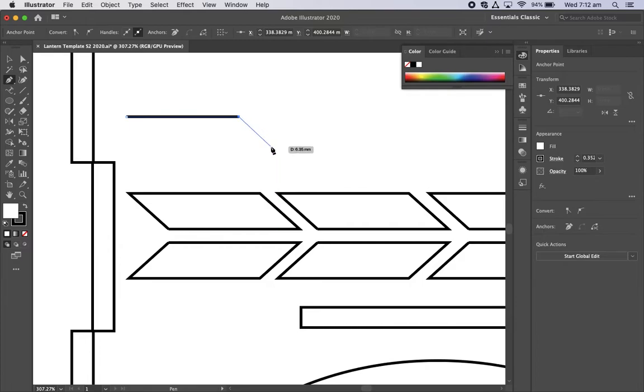Now I want to create a 45-degree line here, so I'll hold down Shift. Good. And at this stage, rather than trying to get everything to line up perfectly, I'm going to overextend this line. Perfect. I'll hit Escape, and then I'll start fresh from this point. Now I'll extend through here, hold down Shift, and now I have the shape I want with a little bit of excess.